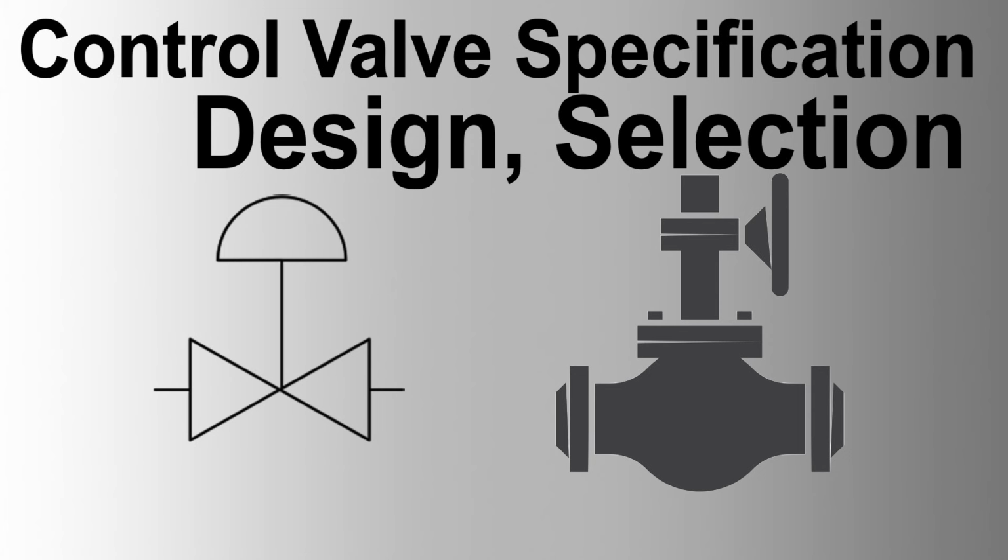3.3 Valve trim, minimum SS 316L, with options for stellite or other hardened materials for erosive services. Characteristics: linear for level control and gravity service, equal percentage otherwise. Quick open trims for on-off valves. Leakage: maximum allowable seat leakage as per ANSI FCI 70.2, typically class 4.